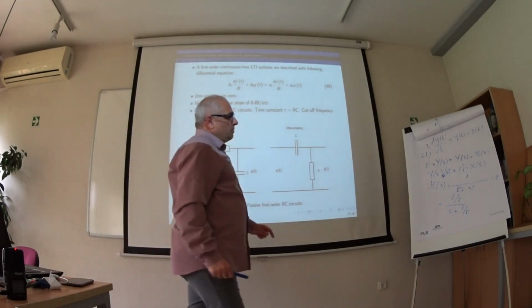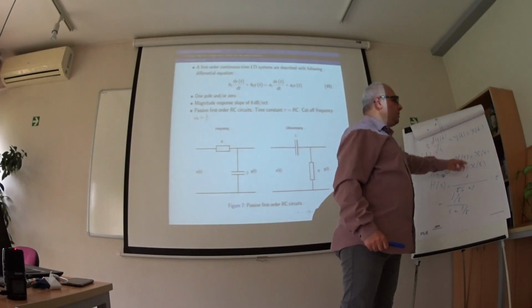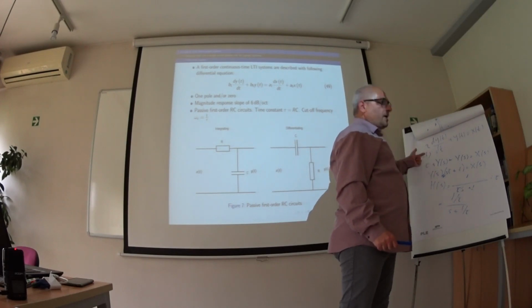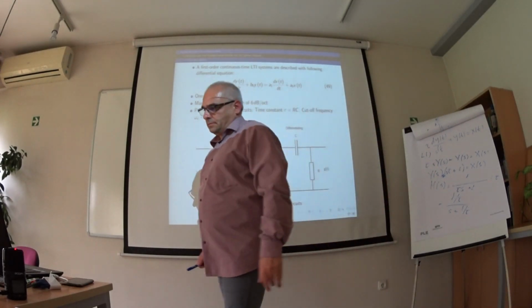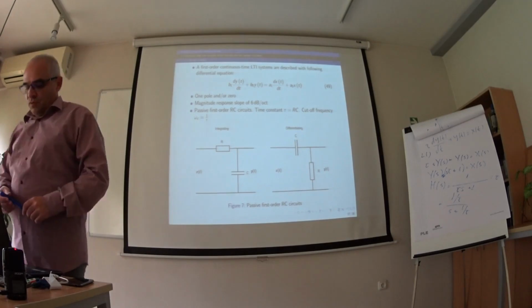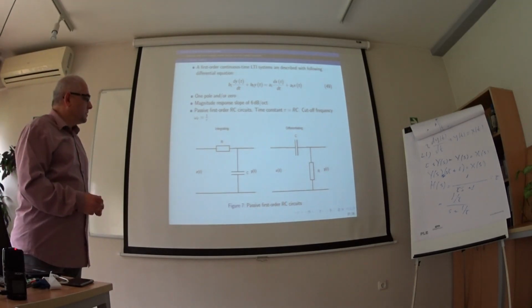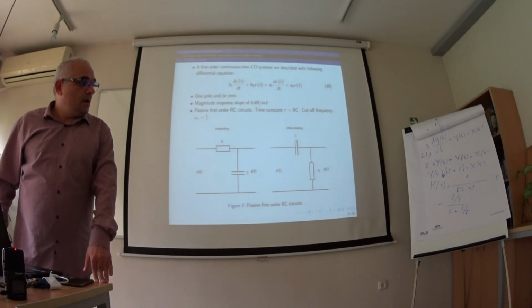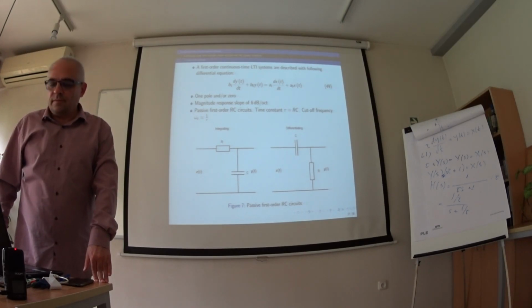Just apply the Laplace on the differential equation, use this property. When we differentiate, we have to multiply by s in Laplace domain, and the things are relatively easy. This transform is very useful when we have to analyze transients in electrical circuits.